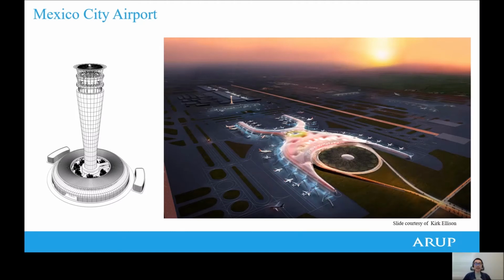Therefore, when analyzing the structural response in design for response history analysis, considering just the superstructure with, let's say, a fixed base might not be accurate. So the soil domain as well as the foundation needs to be considered in the analysis. Therefore, again, LS-DYNA has been used to conduct this kind of soil structure interaction analysis of this control tower to obtain the demands on the structure and the soil in design.